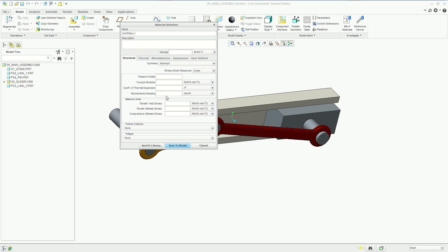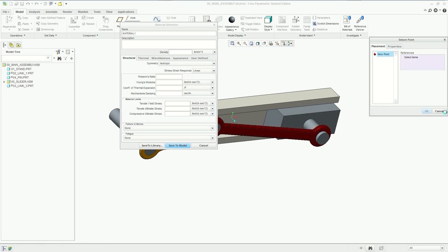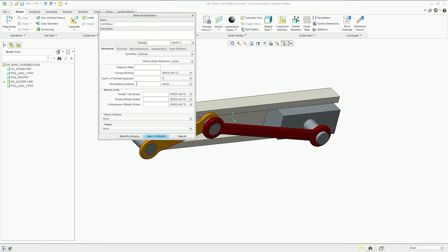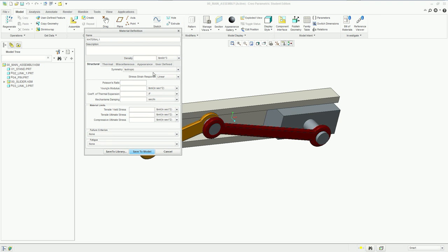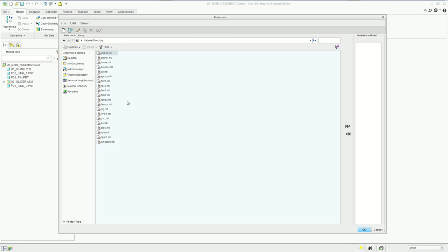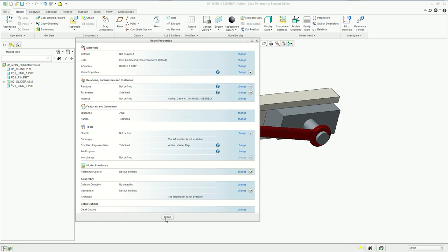So you can look these things up online and make your own materials, and then you can save them on a flash drive in a folder of your own, where you can have your own material library, which is what I like to do, because you don't want to keep reassigning materials and keep saving them. You want to have it all saved in one folder, and have a convenient spot to look up the MTL files. So you're going to save them as .mtl files. Alright, so that's how you do material properties.